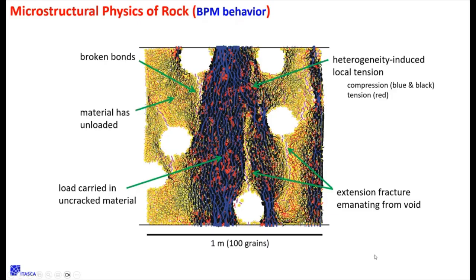And then this is that secondary effect. Because we have those holes, they naturally produce tension above and below, which makes these cracks initiate and grow upwards. This is also what you find in experiments that are done on rock that has holes. They start to fail above and below, and then the macroscopic fractures line up with compression. And we call this axial splitting. This is what we observe in the laboratory for UCS tests mostly. You see these columns of material and it breaks into columns.